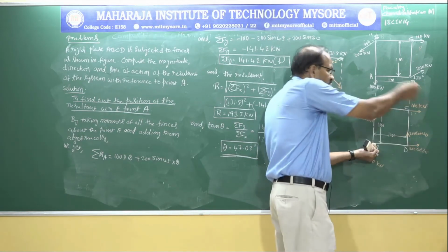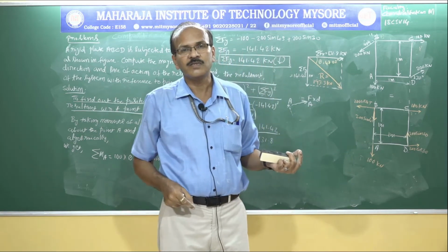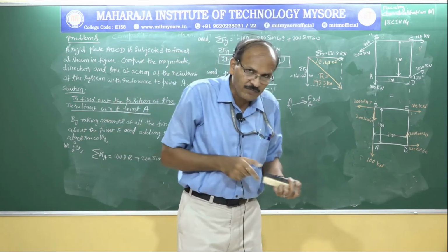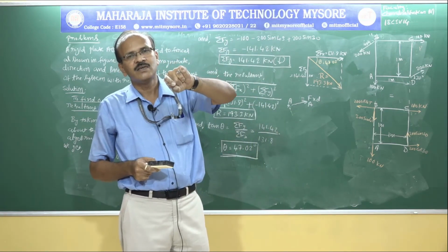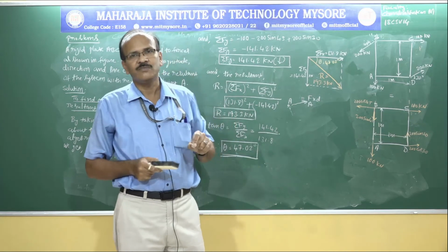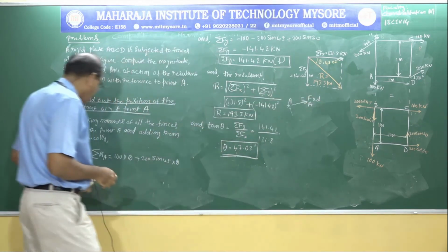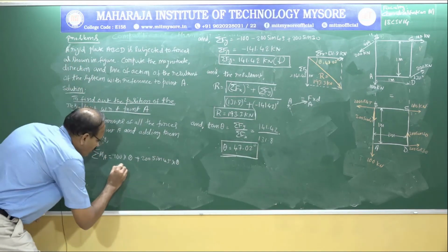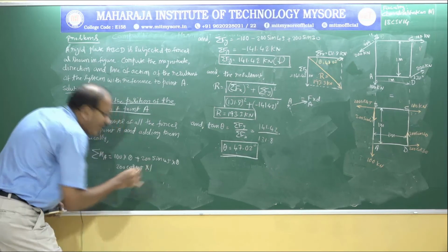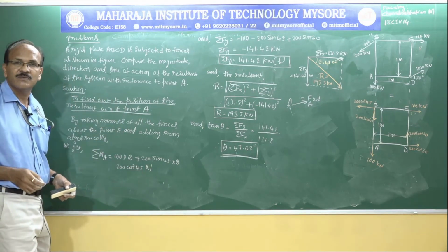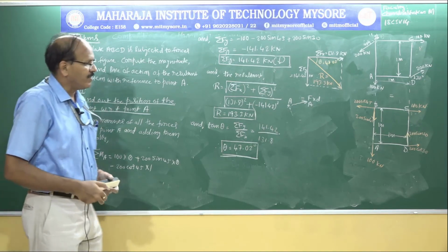Then this traces an anti-clockwise motion, is it not? According to our sign convention, any anti-clockwise moment is negative or minus. So that is 200 cos 45, the horizontal force, into 1 meter, the distance, with minus sign because it is anti-clockwise.